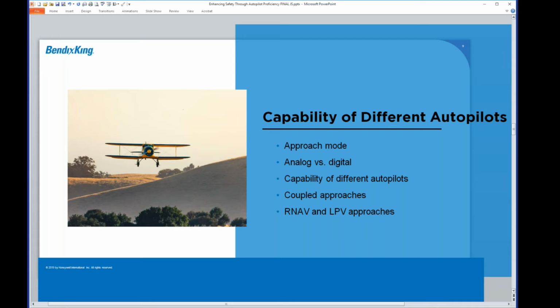And that's a really good thing to clarify, because remember, crab angle is actually what the aircraft has to do in heading in order to correct and stay on the actual track that we want it to track on. But this that we're talking about now, it's an important distinction, because instead of giving the autopilot approximations of what it needs to do to correct for the wind, it gives it absolutes in terms of what angle does this aircraft have to be at, in what bank angle exactly.